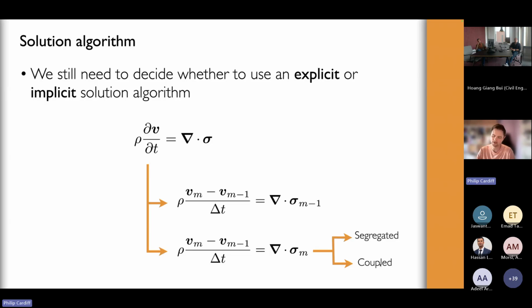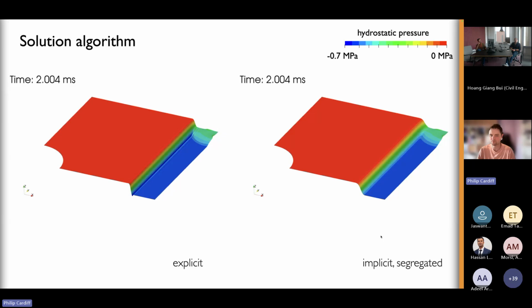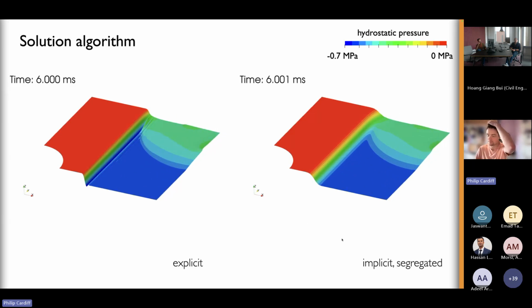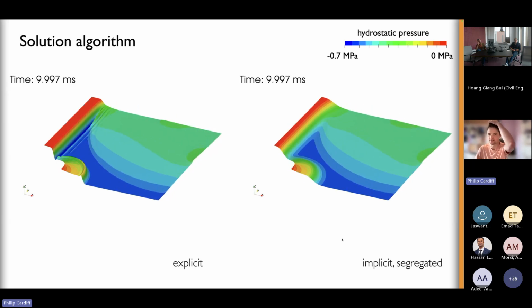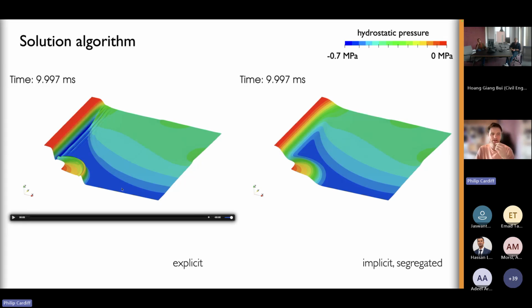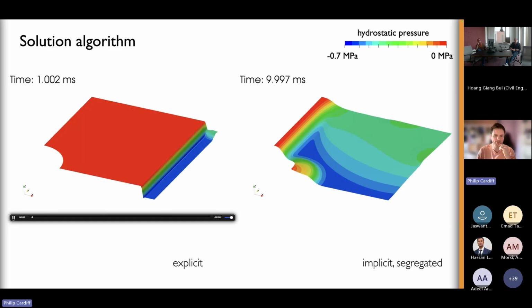But if you look at it from that Newton-Raphson perspective, this segregated approach is called a Picard linearization. So it's essentially a type of quasi-Newton method. So there's definitely similarities you can pose in the same kind of framework. But for example, the same implicit, explicit characteristics you might see in finite element methods, you'll see in finite volume methods as well.